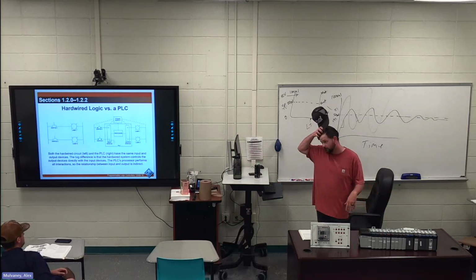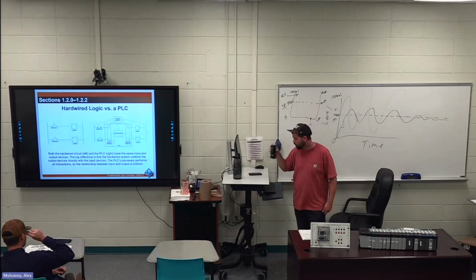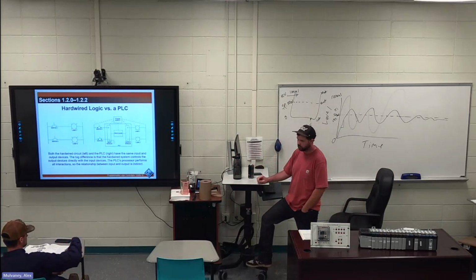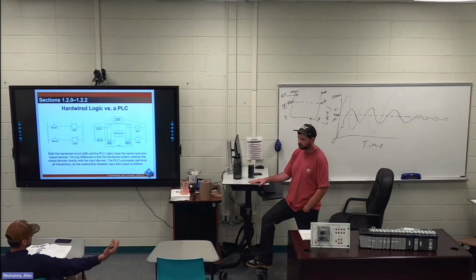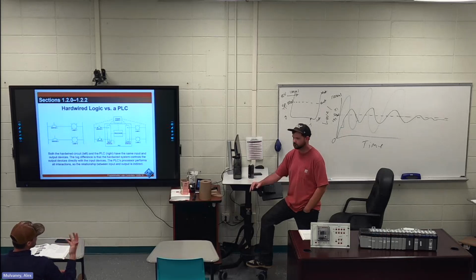Yeah. So I was on an LNG barge yesterday. And the way they have it set up, they got these cryogenic valves, ball valves. They got the actuator on it, and they got an indicator that sends back feedback of whether it's open or closed. They got a line that comes through a regulator, through a solenoid valve, through two needle valves, into the actuator to give the air to open. Mm-hmm. And it's a spring return actuator, meaning when you take air off, it's going to shut, it's going to close.